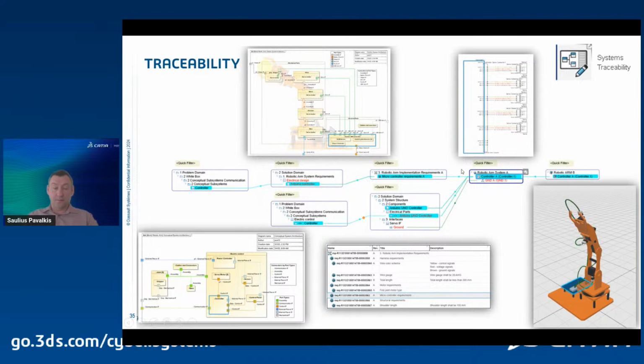Some of those links are manually created between CAD and the SysML model, manually created between CAD and electrical, extracted between requirements and SysML, extracted because we had a data hub synchronizing. Here we had electrifying CAD, so those links are reused. Also SysML between problem domain and solution architecture, automatically extracted. We don't need to update those links. Just the ones in our project between CAD and electrical and SysML, to SysML pretty much, because some of those electrical components go directly to SysML.